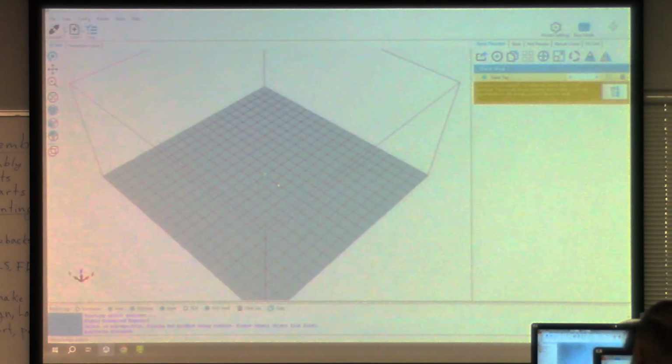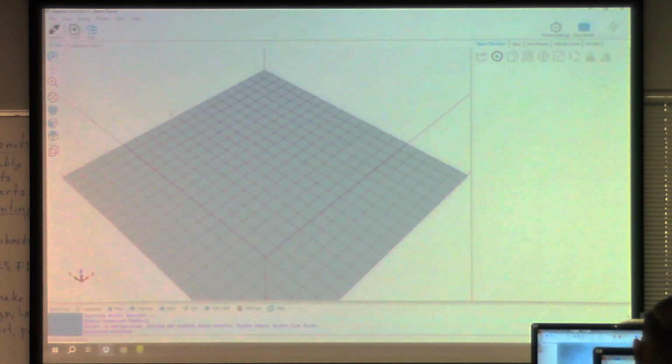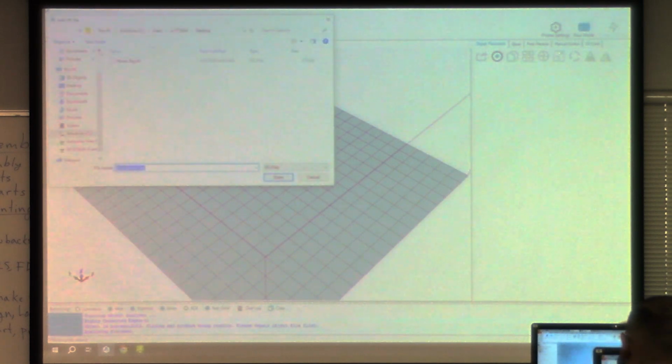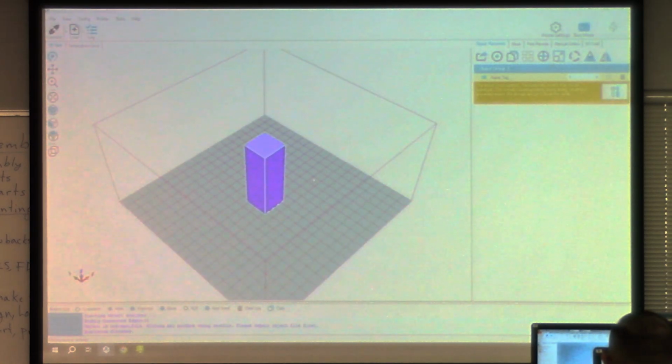Oh yeah, so that doesn't look quite right, huh? That looks way too small. And so I'm going to get rid of that. The reason is that I didn't set up this printer software yet. So this printer also has settings. So up here, there's units of imported objects. We need to change that to inches as well. So we exported our part in inches. We need to import it in inches as well. So we did that. So now we'll go back to this name tag file. There we go. So that's better. So now this name tag is right in the middle of our printer bed.